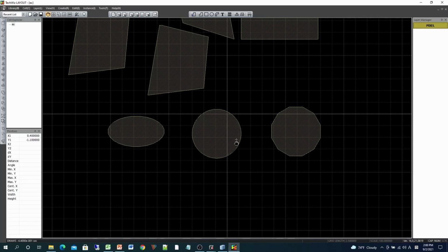However, forming a circle with a large number of nodes is not a good way, because if the mesh length is too small, divergence can be induced. So I totally recommend using 10 to 12 nodes. When designing the layout, most of the circle-shaped masks will be via holes.